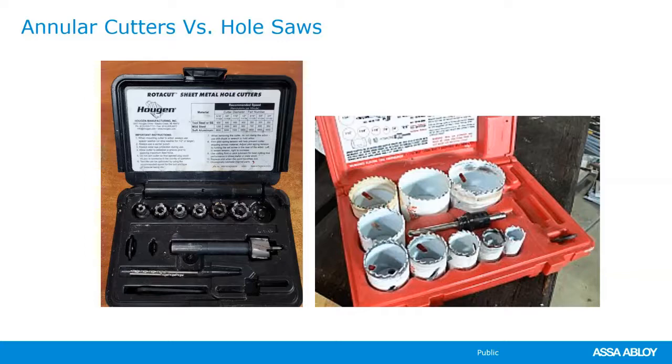It's more of an egg-shaped hole, an oval. And the inside is razor sharp. They're just very, very sharp because they kind of scoot through the hole instead of cutting it. So I'm not a big fan of hole saws when it comes to metal. Now, if you were using a hole saw with a drill press and drilling thicker material, maybe that's fine.